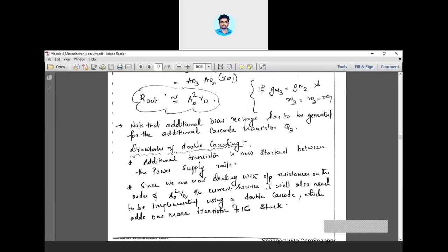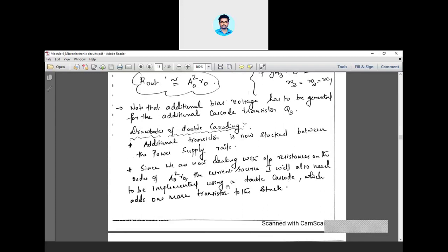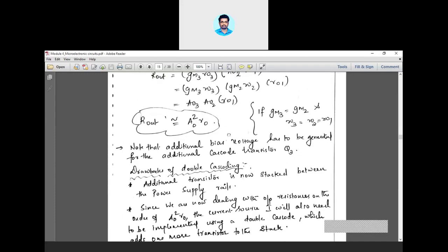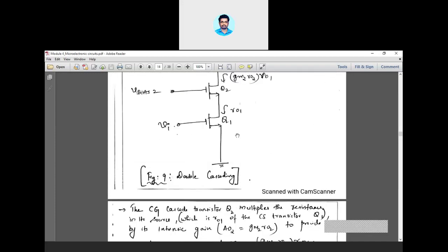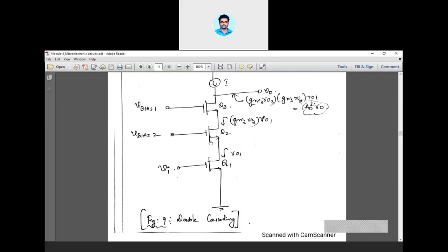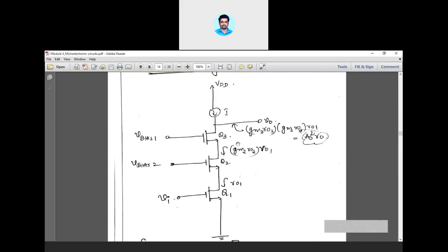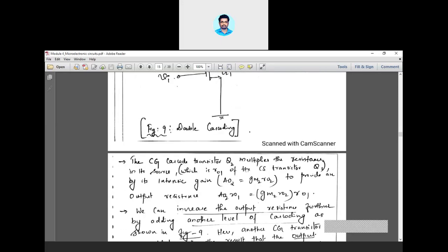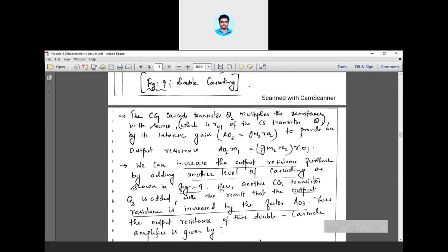Under one power supply you are using more transistors, which yields higher power consumption, I mean higher power dissipation also. So the entire IC will get heated up very quickly because of the use of much more hardware under one power supply, because you are using only one power supply VDD. Under this supply rail you are using three transistors together, so that will yield more power dissipation and your transistors will get heated up much faster.